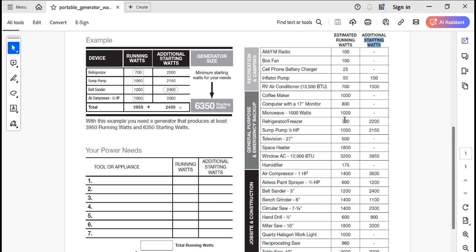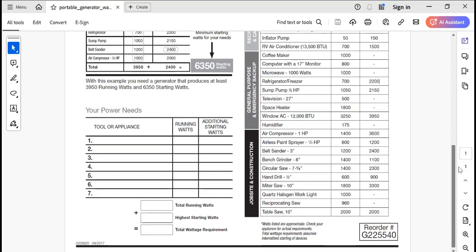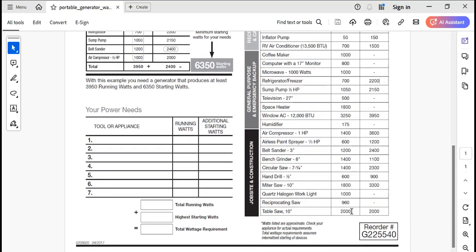So first of all, list the devices, the appliances, the equipment that you want to power from this inverter, and next to each device or appliance or equipment, put the wattage. You can get the wattage from the user manual for each of these items, or there's generally a sticker on things like the refrigerator, the laptop and so forth. Or you can look at the adapter or the power cord. It will generally give you the wattage there. If you do not see the wattage, you can multiply the voltage times the amperage to get the wattage.